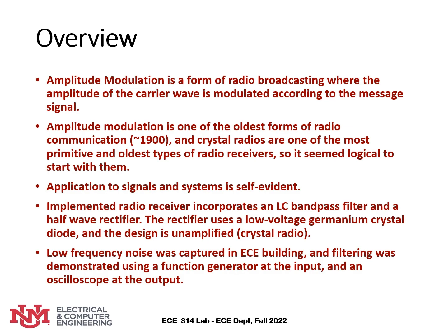My implemented radio receiver incorporates an LC bandpass filter and a half-wave rectifier that uses a low forward voltage germanium crystal diode, making it a crystal radio. I managed to capture some low frequency noise in the ECE building and managed to demonstrate some filtering using a function generator at the input and an oscilloscope at the output.